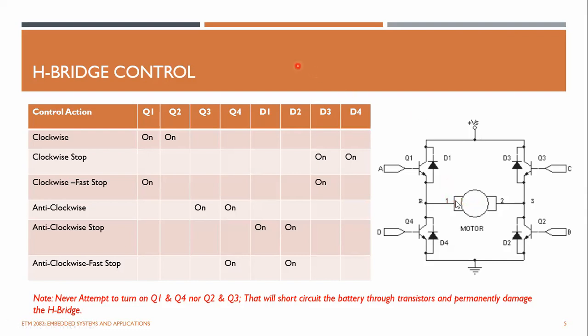Right. So think about it, if you want to rotate the motor in the clockwise direction this way, we need to have plus and minus in this way, right? If you want to rotate the motor in the counterclockwise direction, you need to provide plus on this side and minus on this side, changing the polarity. In a DC motor, if you change the polarity, the direction will change.